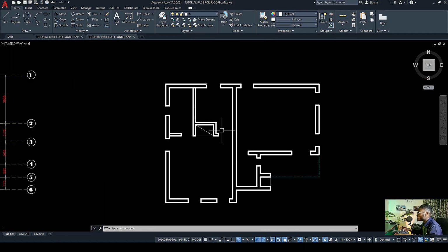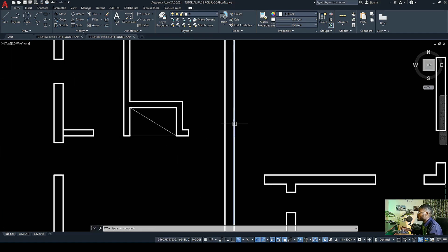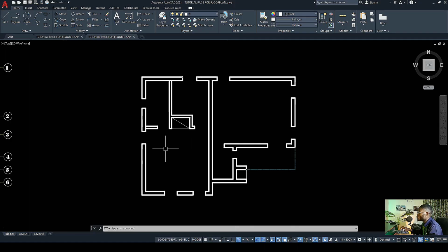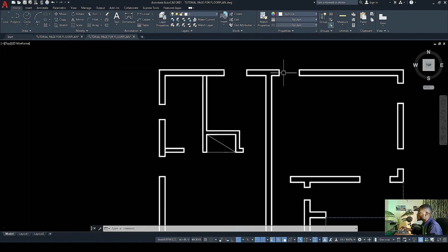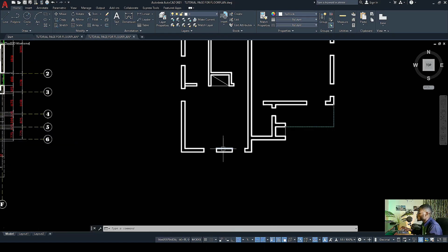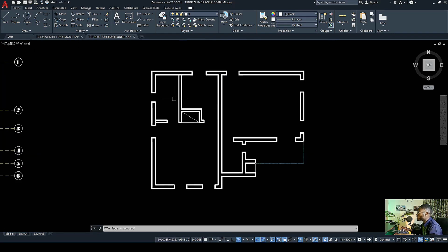We drew all the spaces, added our line weight, and also created our fenestration, our doors, and our windows. Right now we are going to move into sending our walls into their layer, and we also create layers for our windows and other parts of our floor plan we'll be designing. All right, we'll dive into it straight away.